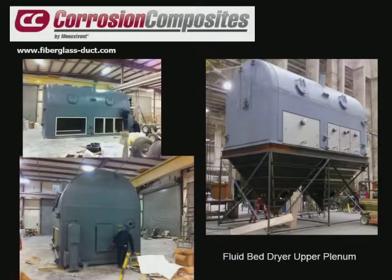What they're doing is they're drying CPVC powder, and the powder is blown through this as it dries. And the problem with CPVC powder is you can get hydrochloric acid condensate in there. So there's a real corrosion problem. It operates at about 180 degrees, and the condensate is very, very corrosive. And we also have a problem with dust collecting in there, and so they have to occasionally beat on the sides, and fiberglass is a very good example.